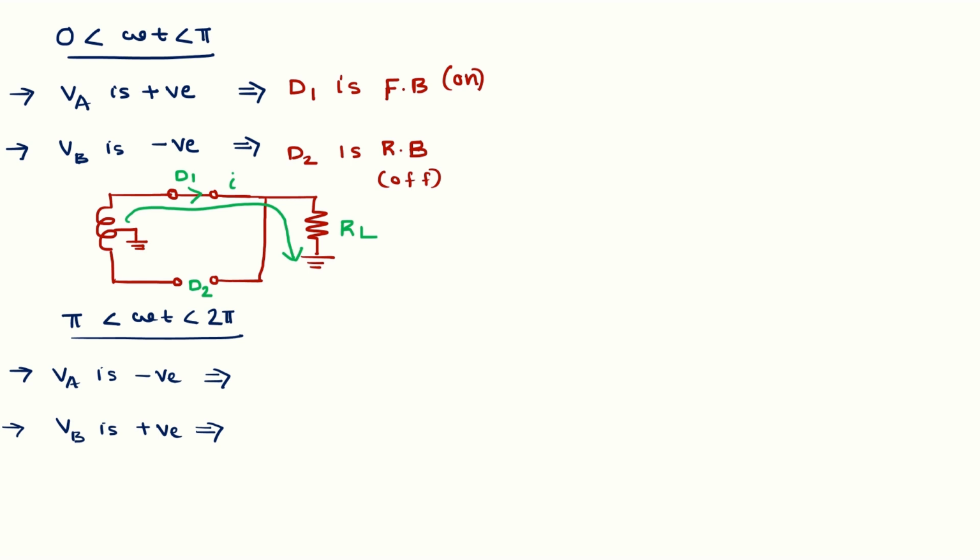Okay, and this voltage is VA. This voltage VA appears across the load resistor. Actually this is V0, the output voltage, which is the same as VA. Because look at this diagram, the RL gets connected to node A. This is node A. RL gets connected to node A through the diode D1.